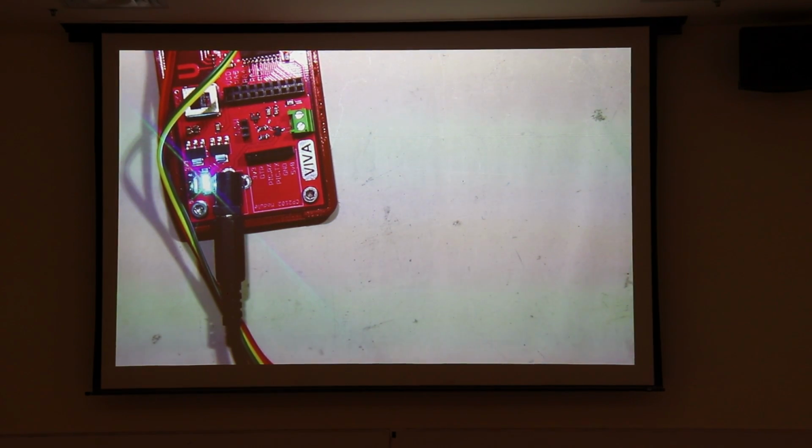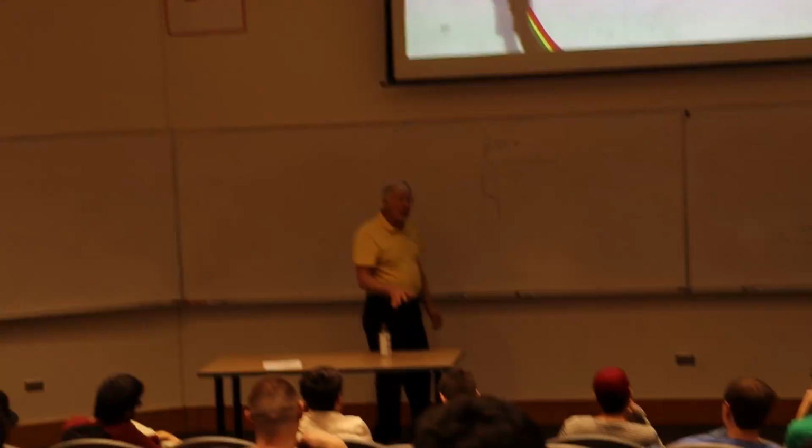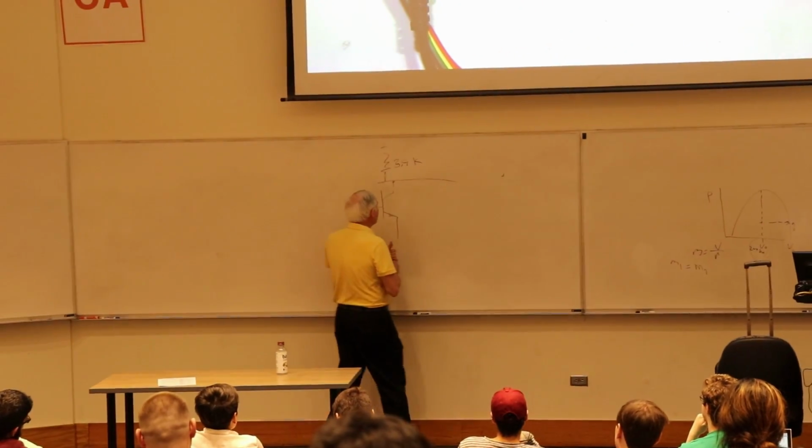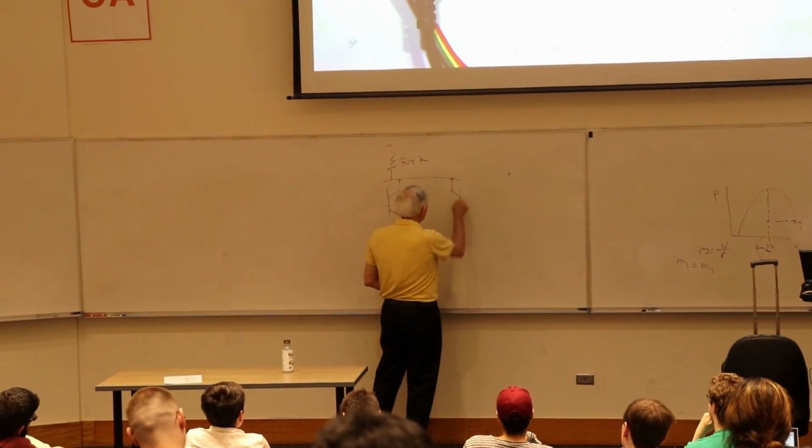Everything connected to this bus is set up this way, for both the data line and the clock line. When you want to send a high, you just let your open collector transistor turn off, and the line floats high through this resistor. When you want it to be low, you turn your transistor on, and it pulls it low. So you can drive it low, but you cannot drive it high. And that's so that you can have another device also hooked on here.